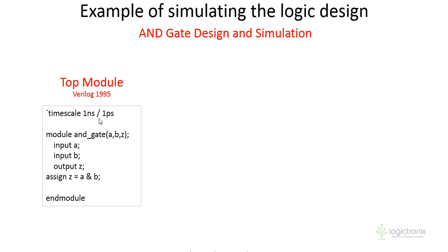This signifies that we want our timing variables to have nanosecond by picosecond precision. It gives the precision of timing which can be needed in the program. The picosecond gives us up to picosecond precision. So if we write timing variables with some value, then it will count up to picosecond, which we are also going to talk about on the next slide.